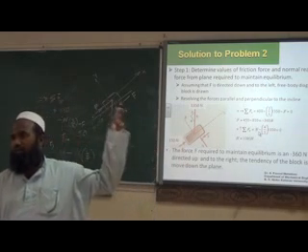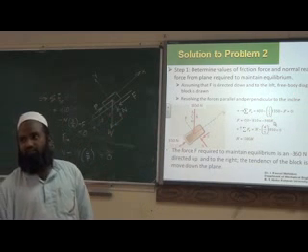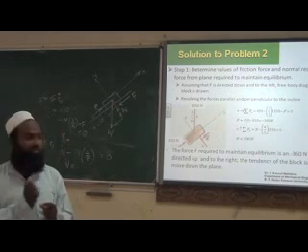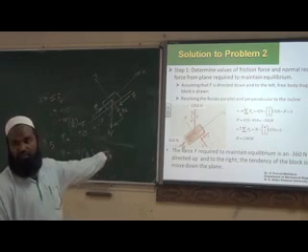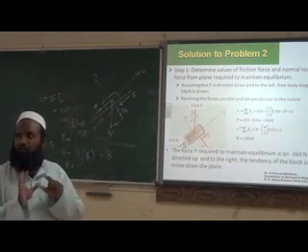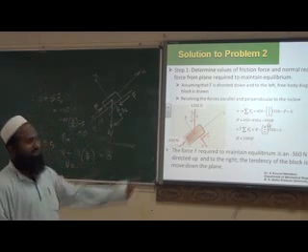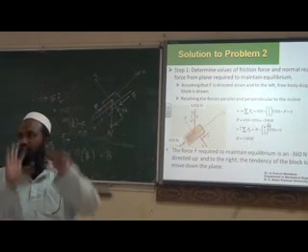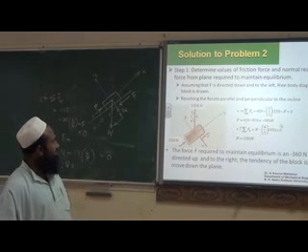So first we find out F and N. F we got minus 360 Newton. That means your assumed direction is wrong. So the frictional force acts in the upward direction, the same direction as the applied force, because the block moves up. Minus 360 Newton. This is 450 Newton. Frictional force is 360 only. So the magnitude is less than the applied force, so the block will automatically be moving up.